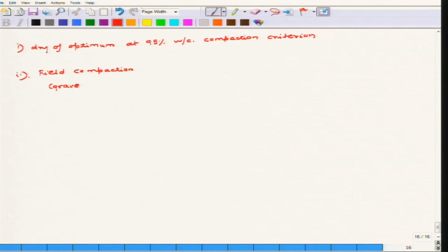Now, again you have to remember here that it is a gravelly sand. So, generally a sand type of soil is compacted by a vibratory roller. So, here also, since it is a sand and gravelly type of soil, it is a coarse grained soil. So, adding water or using a tamping method will not work. So, here you are going to use a vibratory roller.